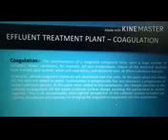When the metal salts are added to water, hydrolyzation is exceptionally fast and forms a progression of metal hydrolysis species. When added to the wastewater, the charged particles in the colloidal solution neutralize the waste particle surface charge, enabling the particles to cluster together.